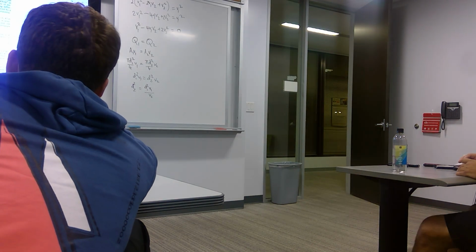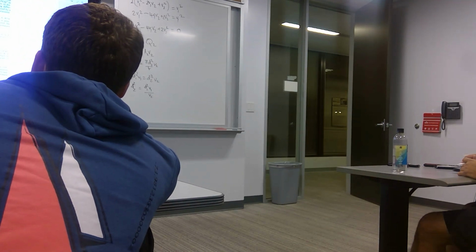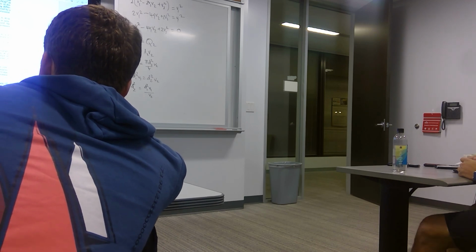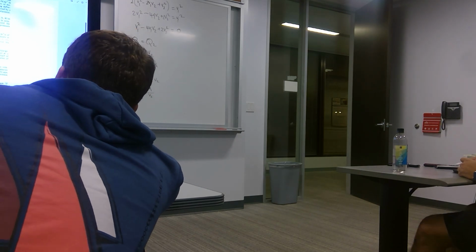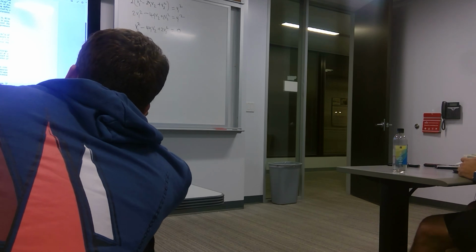Is there any other information we can use? The velocity of 1/2. So we know this, right? We know that the head loss is going to be 1/2 of the velocity head in the pipe.